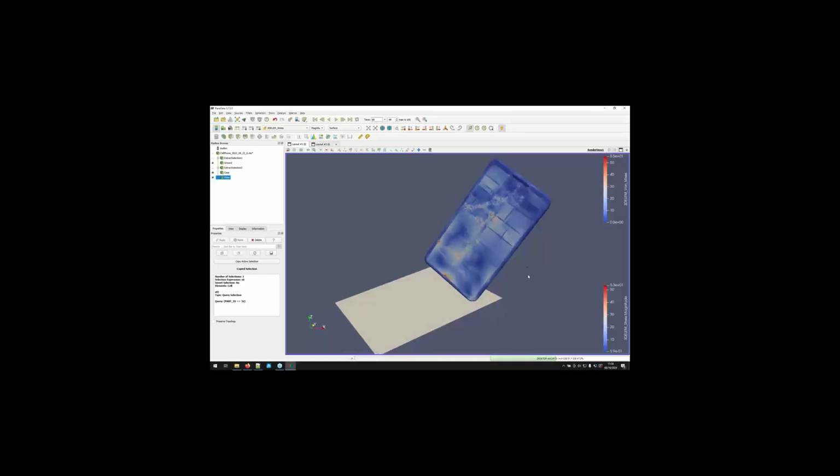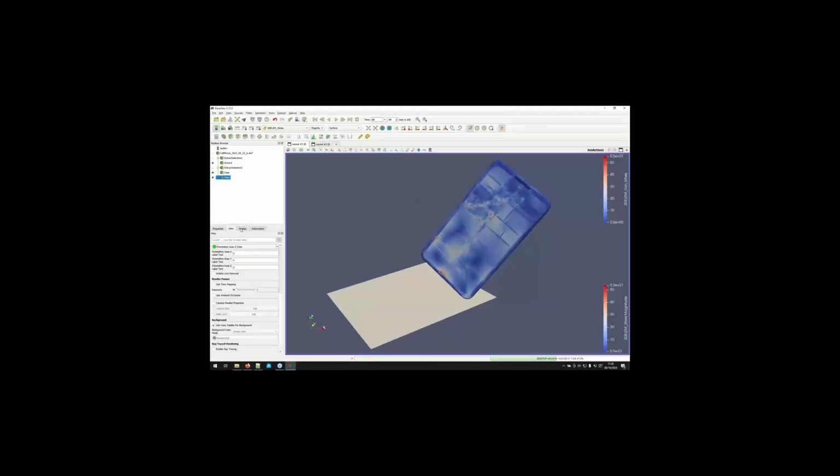Okay, so in the last few minutes, I want to explain how to enable advanced rendering in order to get some very nice images from inside ParaView. So here we have our three parts extracted. So we will activate ray tracing. In the view or everything in properties, if you haven't split it, you can click enable ray tracing here, and it opens a new menu. I hope it's not too small.